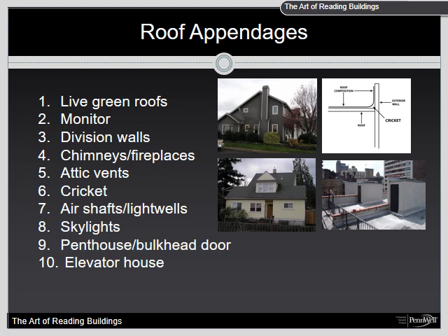Those zero clearances, you have a little small opening for your fireplace, you have some heat resistant brick in there, usually they're gas logs, sometimes they allow for maybe 2 or 3 small logs to burn, and then the chimney itself is not made of masonry at all. It's usually just some sort of wood frame type lightweight structure with a metal tube running up through the center.